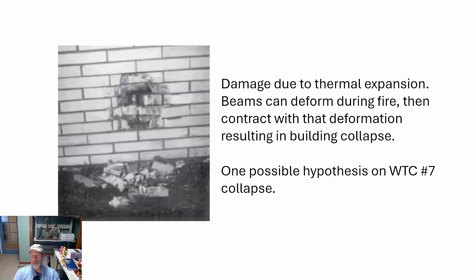Here's an interesting example. Now, this is a decades old photograph. But what you had is a flashover in a basement location. What happened is the beam, as described earlier, heated. That beam then expanded to a point that it knocked out the bricks in this case.